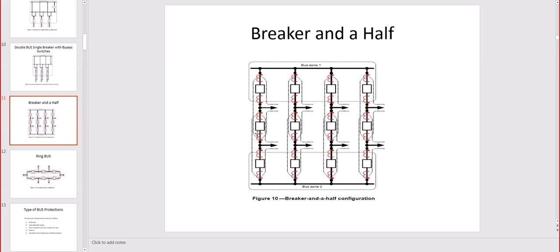Now, for the moment we transfer from one to the other, even if it's a switchgear doing a make before break, the time is so short that we will not size the feeder for the double short circuit. We will neglect that little transfer, and for the time being, we will have the same sizing, either on 1 or 2, in the permanent steady state.